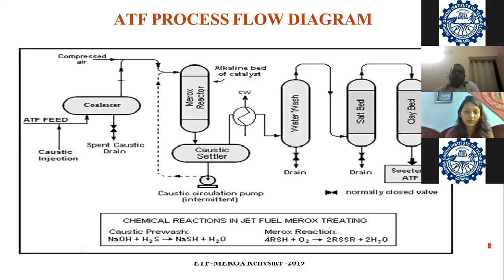The ATF feed is coming from the top distributor of the reactor, and the lower, bottom side is the outlet, also called the collector side or the bottom drain. Inside, the Merox reaction is taking place, and it gives us less than 15 ppm of product. Then the hydrocarbon flow along with the dissolved air flows from top to bottom. The pressure in the reactor is regulated by the system back pressure control valve, and mercaptans are present in the ATF feed stream.